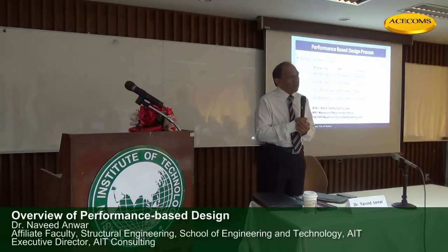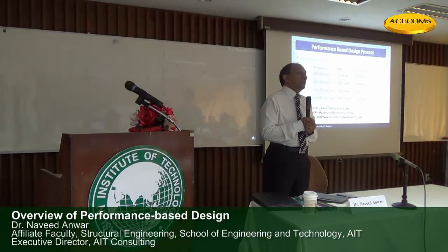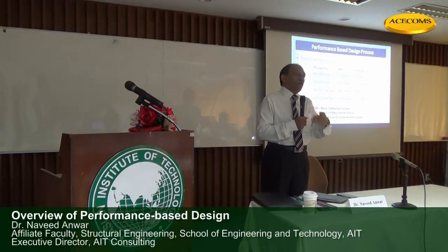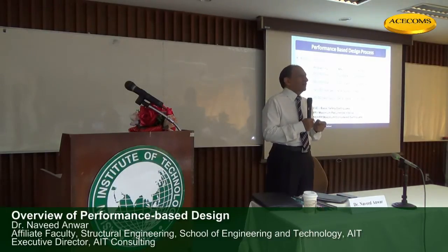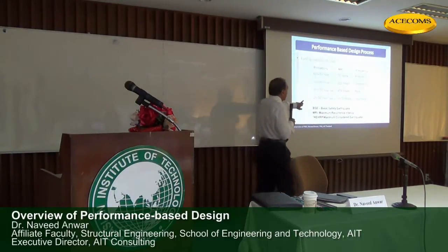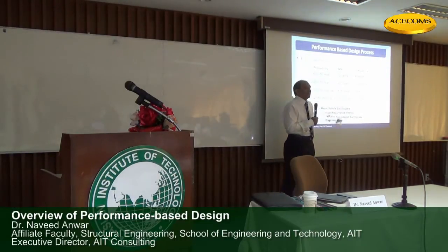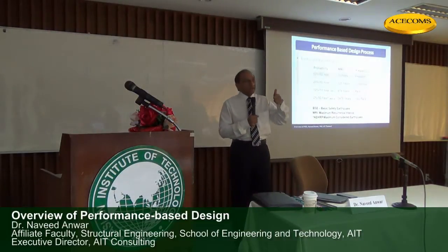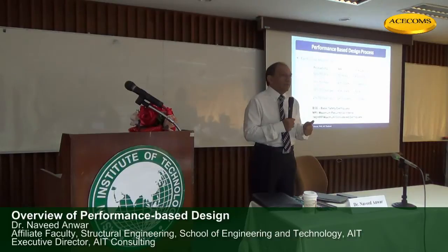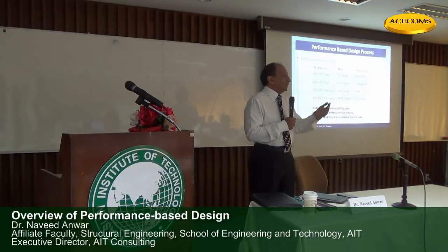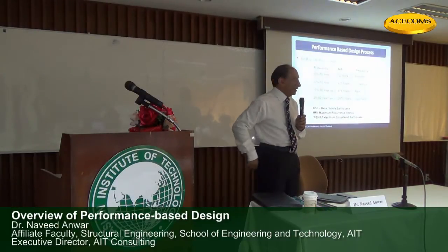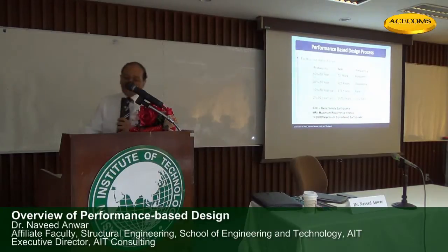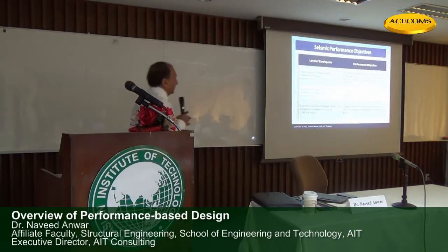On the other hand, we have a project in Bangkok these days. They say it should be designed for a 100-year life, not 50 years. So now the design life of the structure is 100 years, which means now we have to take care of a higher level of seismic hazard because 100 will come here. So this one will be higher. So buildings which are designed to last longer must be designed for a higher hazard level. Buildings which are designed to live shorter can be designed for a lower hazard level because of the probability coming into that picture.